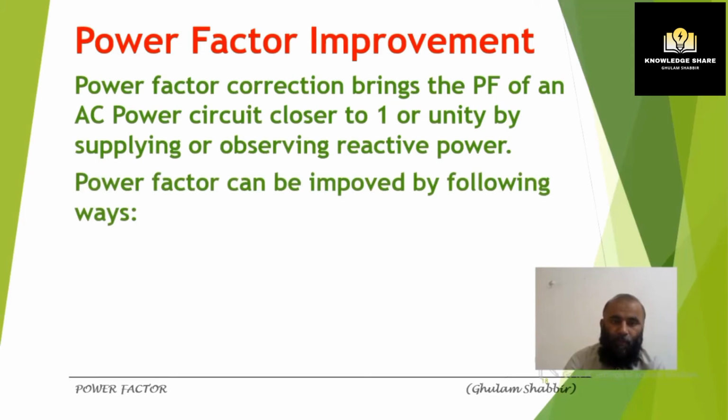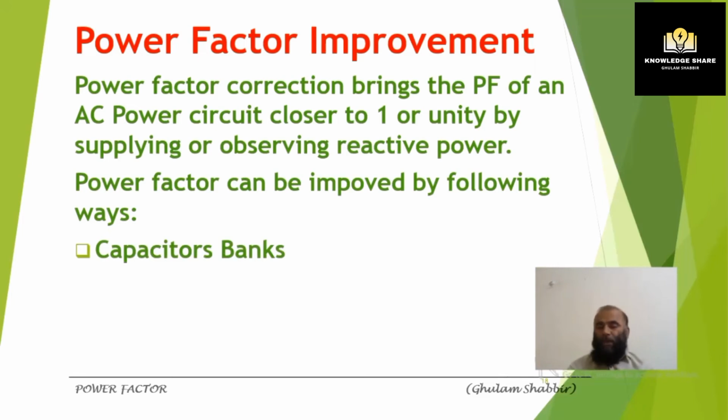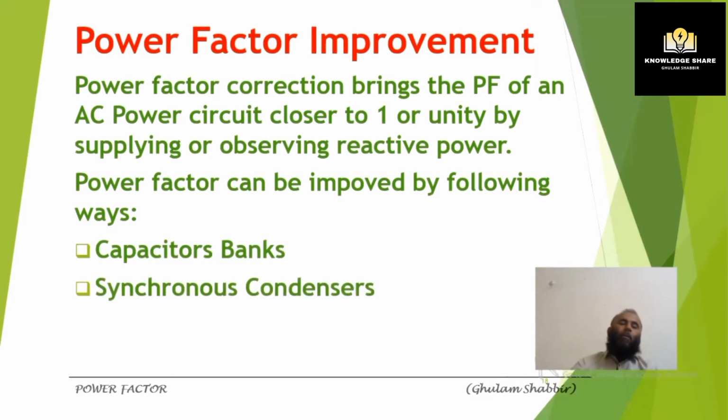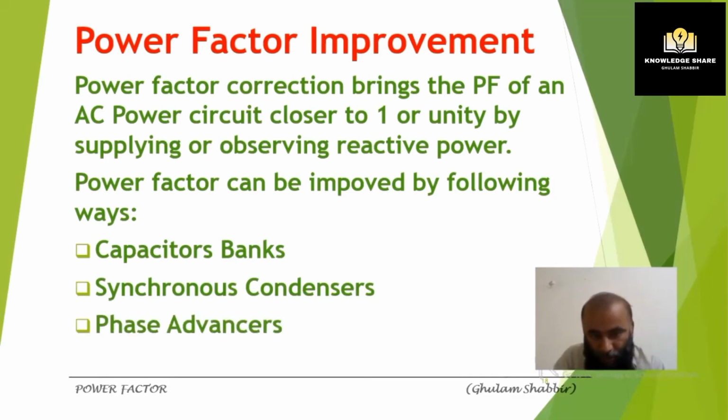Power factor can be improved in the following ways: by installing a capacitor bank, by using synchronous condensers, or by using phase advancers.